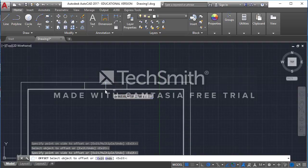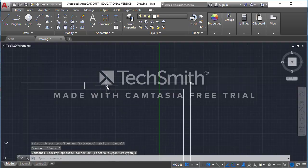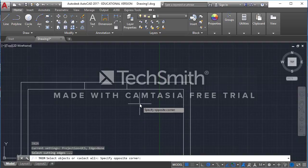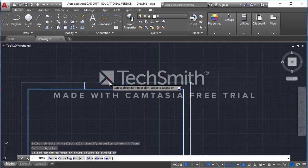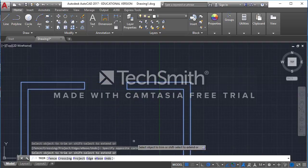Perfect, thank you. Okay? All right, so then I'm going to use my trim tool to trim out the middle of my doorway. So again, TR, I'm going to select all of these lines. I'm going to hit enter, and I could either click on both of these, or I can simply make one selection and click on them both.